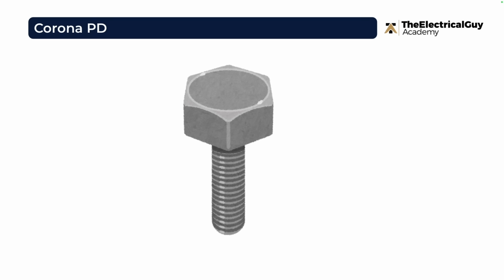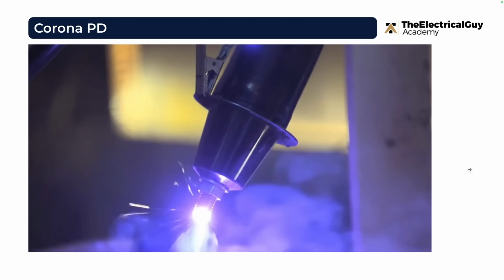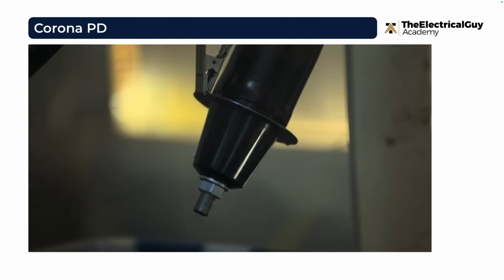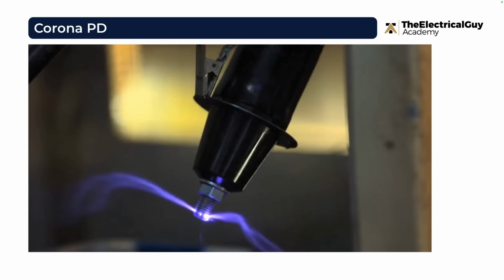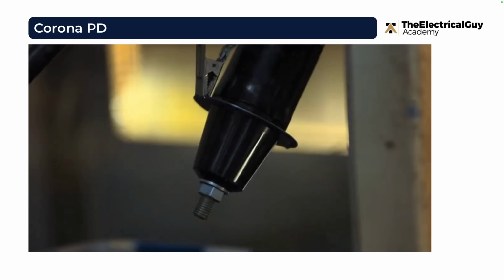But the moment you start increasing the voltage, something happens. The air around the bolt starts to break down because air is not a perfect insulator and it contains a lot of free ions and electrons. And as a result, you will see a violet glow coming out of the bolt, right? And now you may also hear a hissing noise. And this is nothing but the Corona partial discharge.